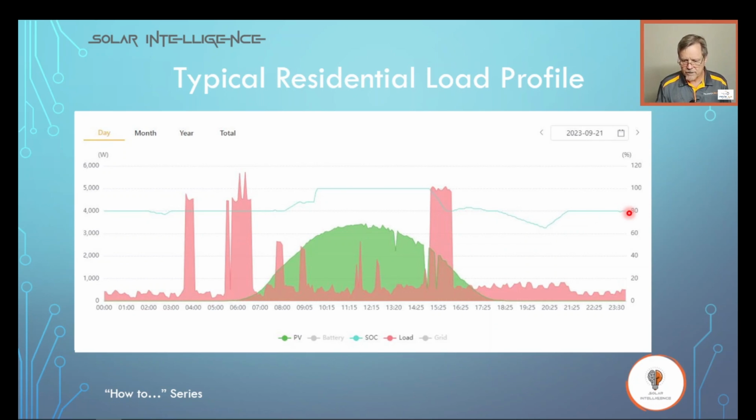So how that basically works, if your inverter is smart enough to do that, you can program the minimum state of charge that the battery will maintain, that the grid will use then to keep the battery stable at that point. So when the battery discharges to that set level, we call it a self-consumption level of 80%, then at 80% it will stop using the battery, it will then start using the grid power, your Eskom power.